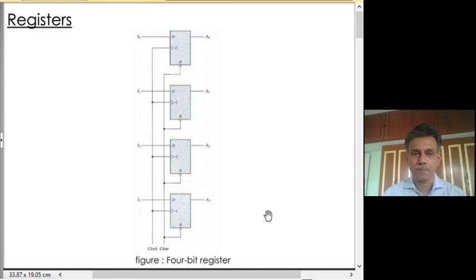while no such gate may be there in the clock pulses that feed other parts of the circuitry where different flip-flops are. As a result of the propagation delay of this gate, the clock transitions that come to these flip-flops are delayed by the propagation delay of the gate as compared to the clock pulses that go to flip-flops in the rest of the circuitry. Because of that, a problem called the clock skew problem comes. That is, the clock transitions occur at different times. This can become a severe problem, one, in a large circuitry, or two, when you operate such circuitry at a high frequency.